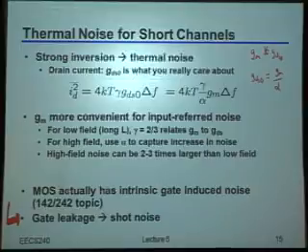So in other words, it was within the realm of definitely bipolars and not MOSFETs in terms of gate current to actual drain current. Again, just be careful of that, because if you do have substantial gate leakage, it could also show up as a reasonable amount of noise at the input. You better add that, of course, to your model. Make sense to everybody?